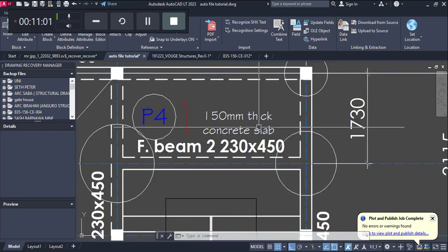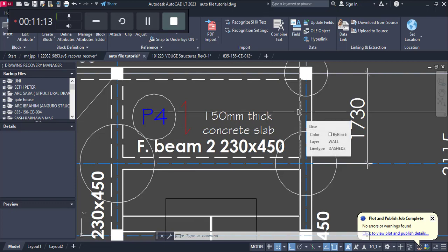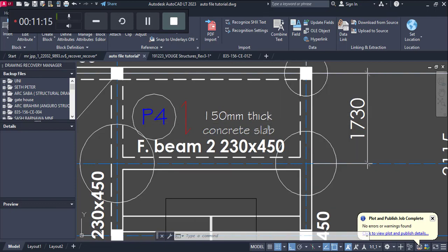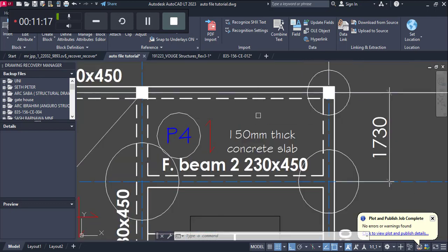And what this actually means is that all your main bars are going to be spread along this, and then this beam here and this beam here are literally not carrying any load. That's basically what it means by a one-way slab. So when they say a slab is one way, that means the load from that slab is only spreading along this beam and also along this beam. There is no load acting on this and also on this.